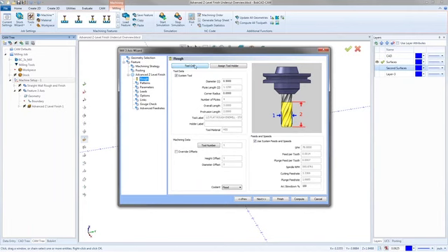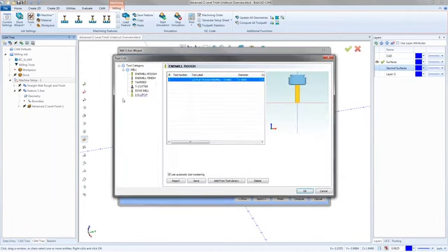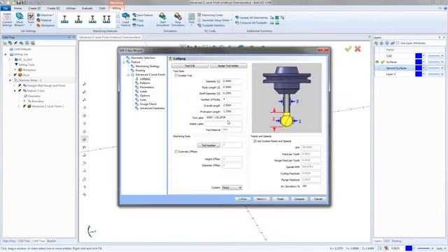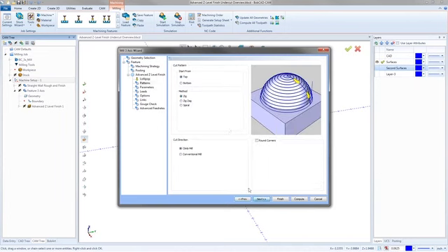Now I can go up to my tool crib. Now inside the tool crib, over on the left here, we can see all the available tools that we can use with this toolpath. And so I'm able to use tapered tools, T-cutters, dove mills, and lollipops. I want to use a lollipop, and I already have one in here. It's a 1/2 inch lollipop with the shaft diameter of a 1/4 inch. So I have an 1/8 inch overhang on either side. So I'm going to go ahead and pick that lollipop and hit OK, and then hit next.